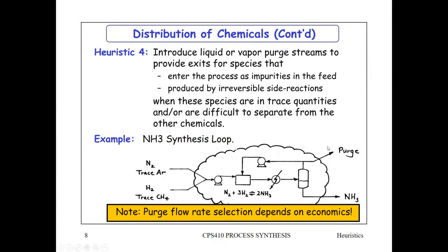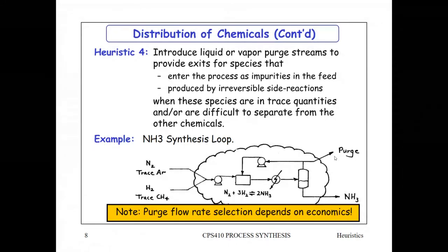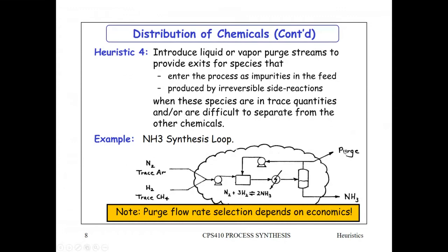The hydrogen would be specifically a valuable species. CO maybe not so. So if you put in a membrane reactor, you can purge that, but the CO you would be able to put into your flare, and it will make CO2 in the flare, and well, that's not ideal that you're putting CO2 into the atmosphere, but it is not toxic at least.